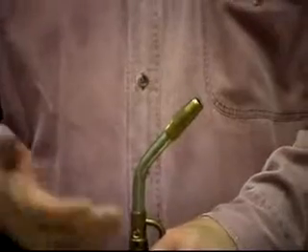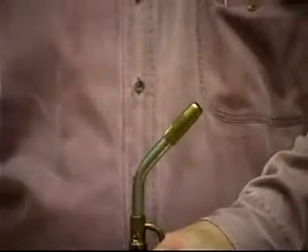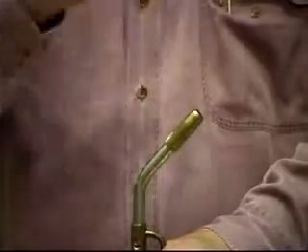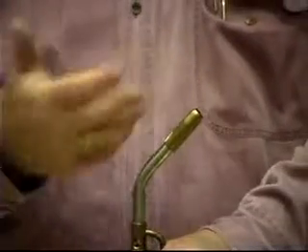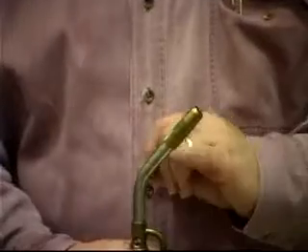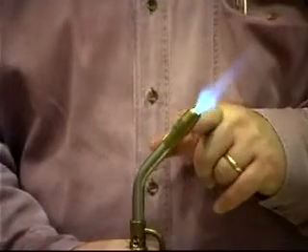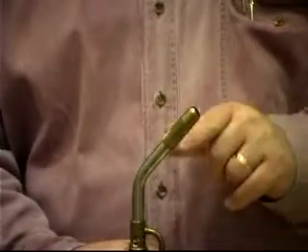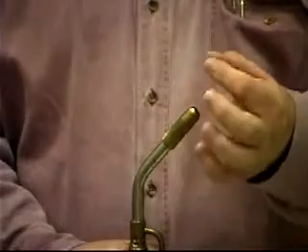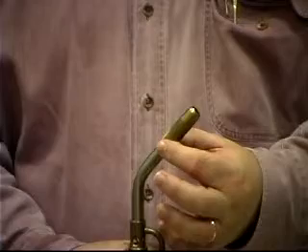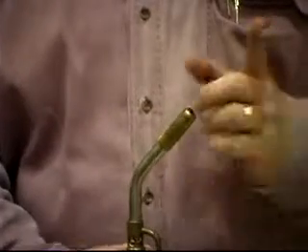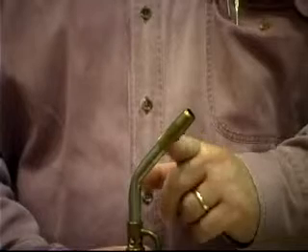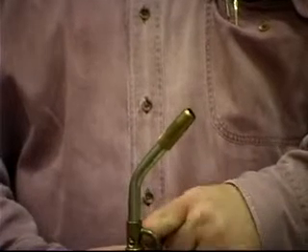When I shut it off, the gas is being shut off and the velocity has to drop to 0. Well, there's a certain burning velocity of the gas depending on the stoichiometric ratio and whatnot. And so this thing is designed not to be burning in this chamber right here, but just be burning, or essentially be pushed out. If my pressure goes down, the flame is going to pull back inside here. And what happens when I actually shut the whole thing off and I get that final little pop, what's happening is it's coming back here and there's a little burning right back.